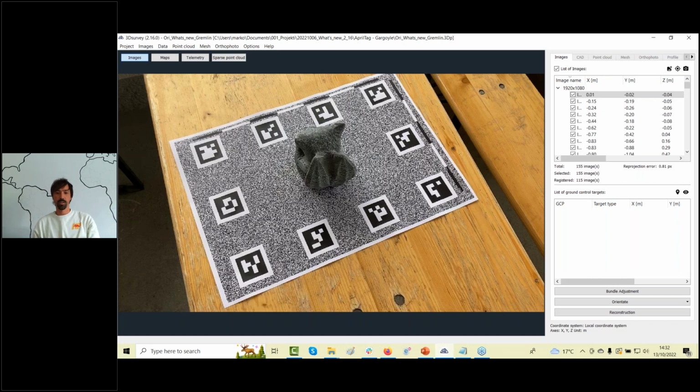or maybe combine them with the 3D survey targets. So let's say you have just 3 April tags and 7 3D survey targets, you could maybe fly lower over an area with April tags and detect them automatically, and then all other 3D survey targets which would be captured from 80 meters would also be automatically detected. Maybe a bit complicated to explain, but that kind of combination would work actually. But let me first show you the workflow with the April tag targets.